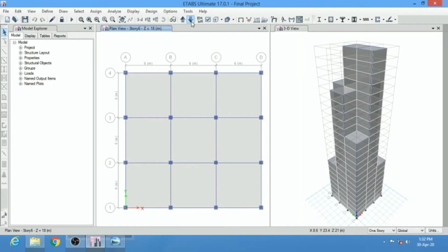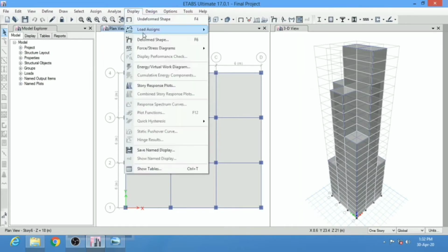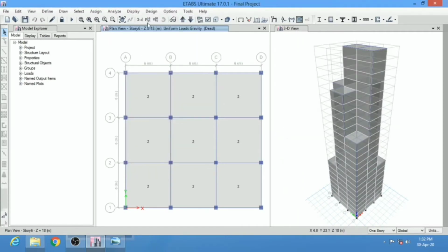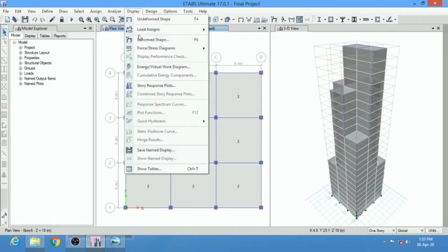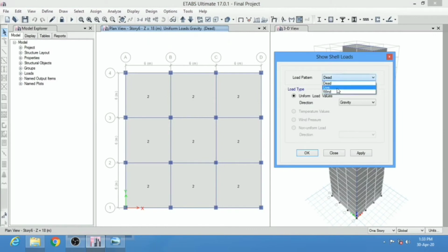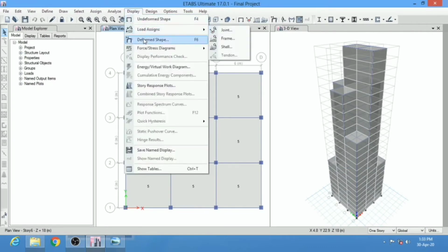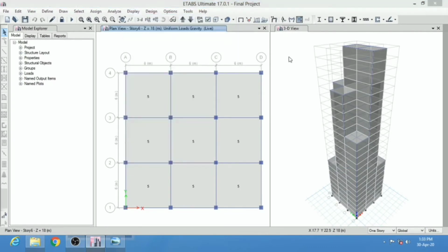First, the wind load. We can change the property to wind load and we can see the different wind loads acting on the different stories. For wind load calculation, we use IS 875 code for assigning the wind load coefficients which are acting on the building.